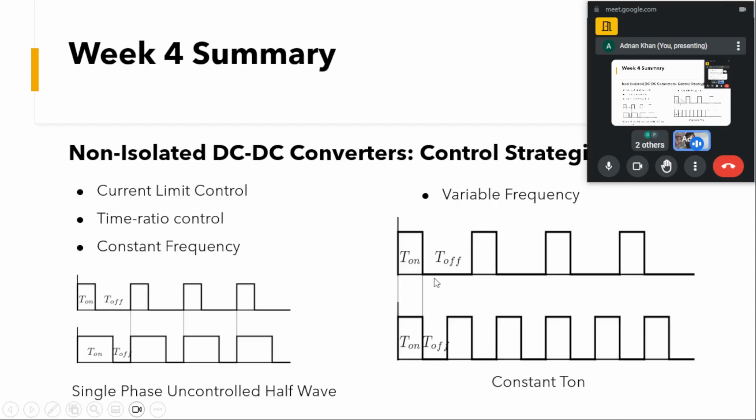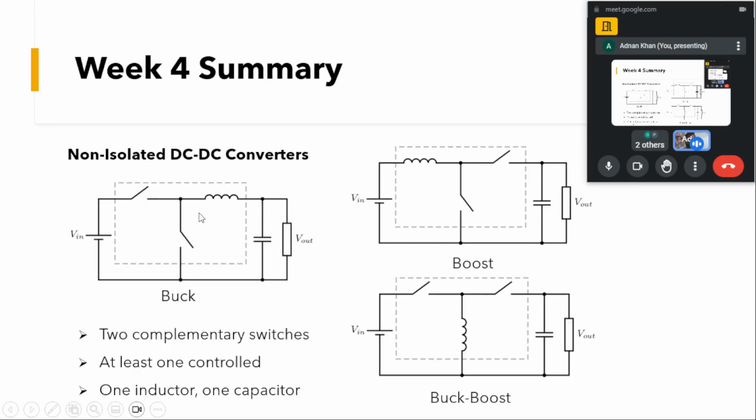I can show you with this example, a buck converter. When this switch is off and this switch is on, and the current is positive, it will flow in this direction. However, when the current through the inductor gets negative, it has to flow in this direction. But if we have a diode here, that diode won't allow the negative current to flow.